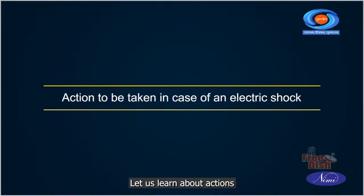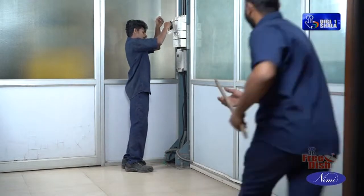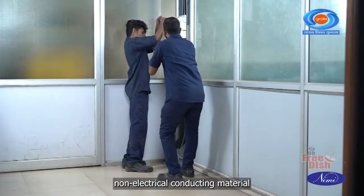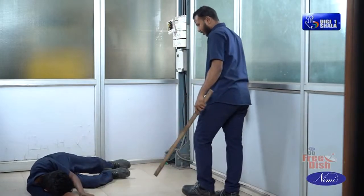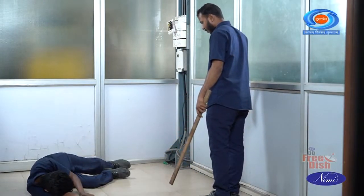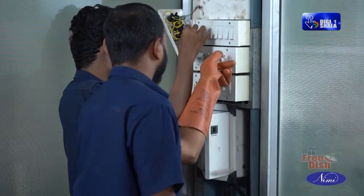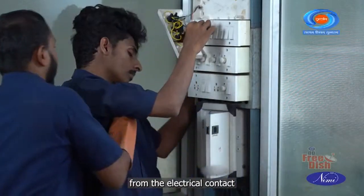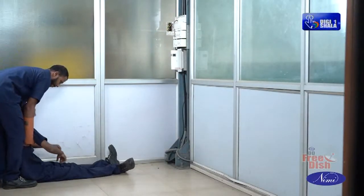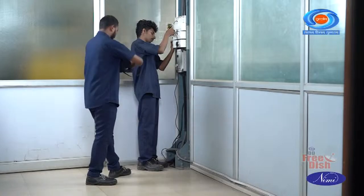Let us learn about actions to be taken in case of an electric shock. If the victim of an electric shock is in contact with the supply, choose the appropriate non-electrical conducting material to release the person from electrical contact, such as wood or rubber. Switch off the electrical power, insulate yourself and pull away the person from the electrical contact. Or remove the mains from electrical plug.